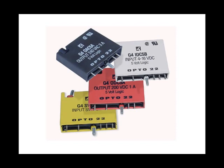The red module is controlled by 5 volts DC output from the controller and will switch field devices requiring 200 volts DC or less at a maximum of 1 amp. The yellow module has a manual switch that is converted to the 5 volt DC input level. Notice that some have 3 pins in place of 2. These are solid state relays that have both a normally open and a normally closed operation.